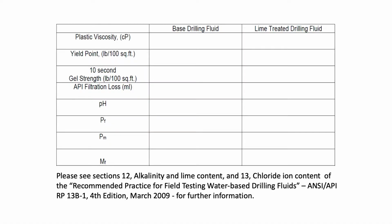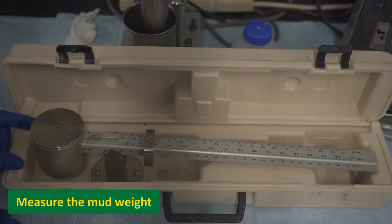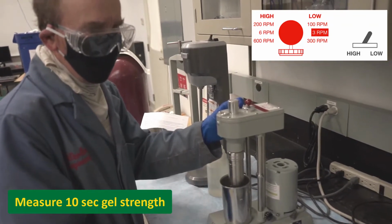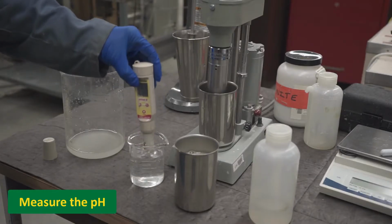Next, several tests must be performed on the base mud, and the results will be presented in the table seen now. To begin, measure the mud weight, the 10-second gel strength, and the pH.